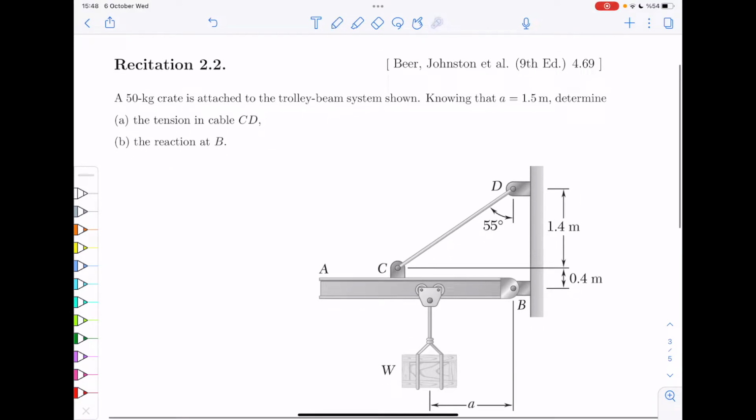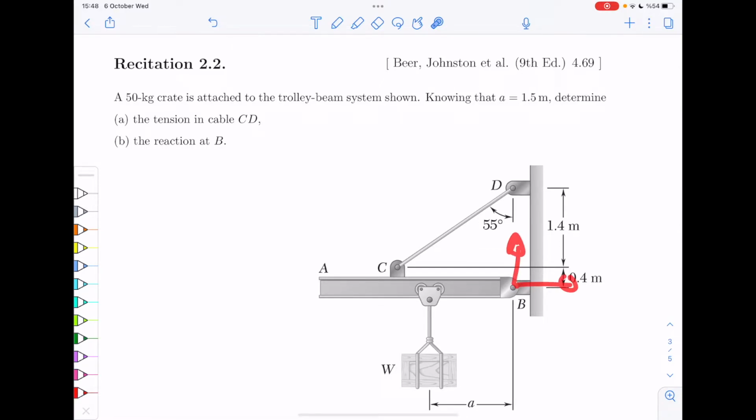So here is the problem. You will have a weight hanging, let's say, from this beam. The beam is attached here by, let's say, a pin or a hinge. So it's something like that. It's a hinge which can apply 2 forces but no moments. So you can imagine there are 2 reaction forces here, but there is no additional moment.